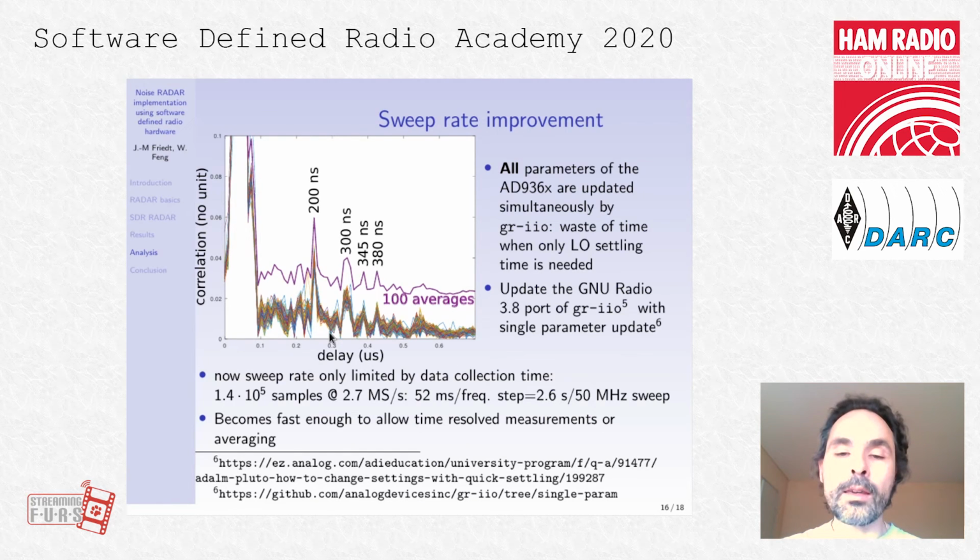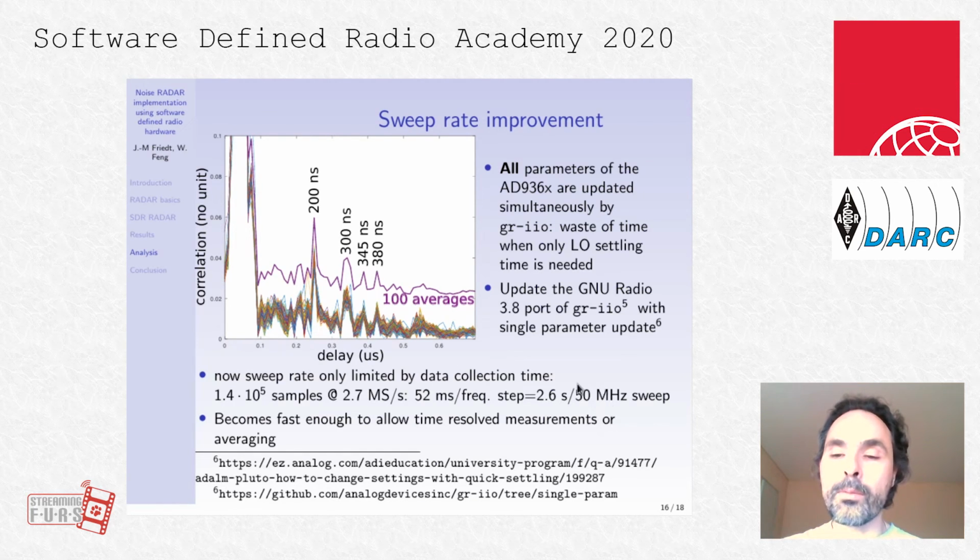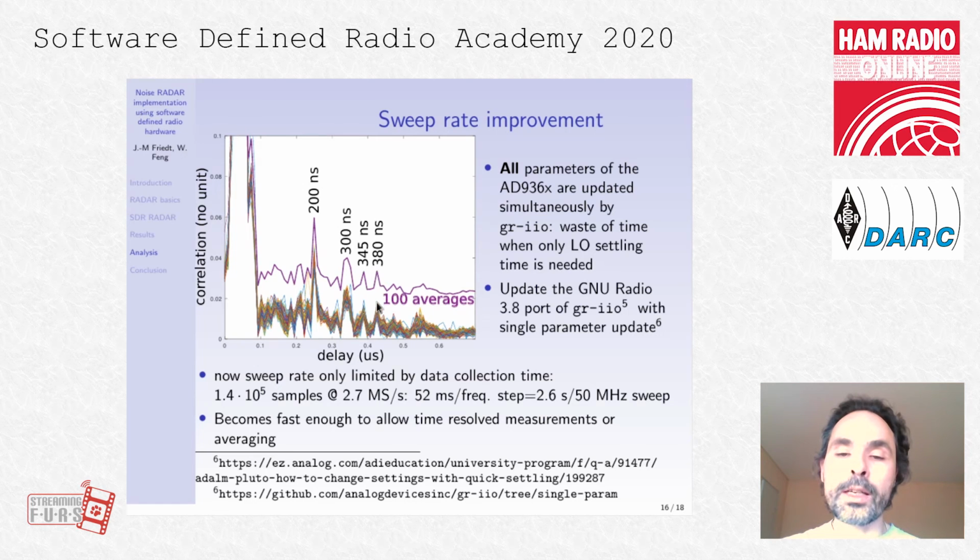So now we can make averages by taking multiple measurements, and you see here the signal-to-noise ratio improvement by averaging 100 averages. The offset was included on purpose to make the chart clearer. So we now have a fast sweep with all these echoes that are attributed to the house, to the chimney, to the tree, and to the car with a very nice signal-to-noise ratio.